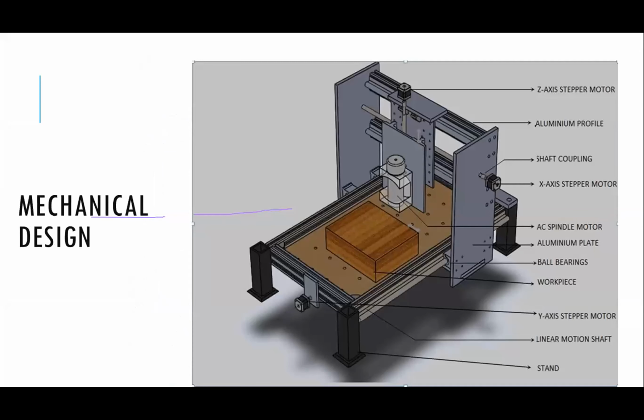So here, a mechanical design. Finally, we have done our prototyping. Maybe we have made a structure and simulated it, and considered what kind of material could be taken care of, whether I need to go with mild steel or I need a cast iron base. Where all could I have a cast iron base? Why is cast iron used? Cast iron is a vibration absorber. So I need to decide whether to use cast iron totally, or only at certain places.